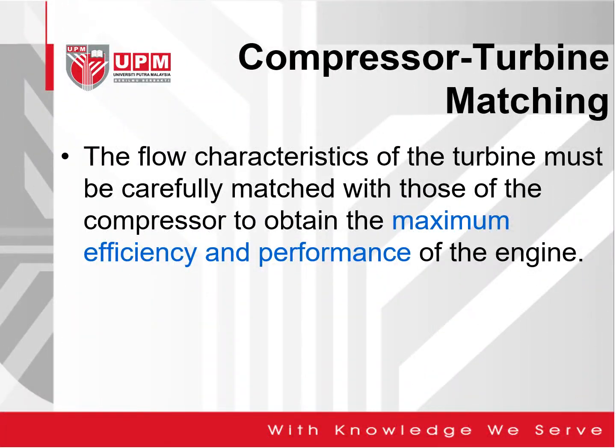With regards to the compressor turbine matching, as you all know, the compressor and turbine are interconnected via a shaft. So the flow characteristics of the turbine must be carefully matched with those of the compressor to obtain maximum efficiency and performance of the engine.